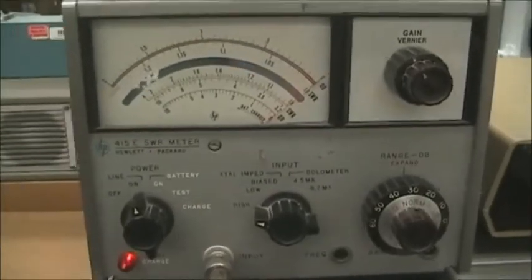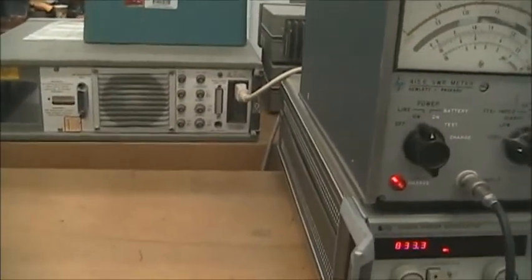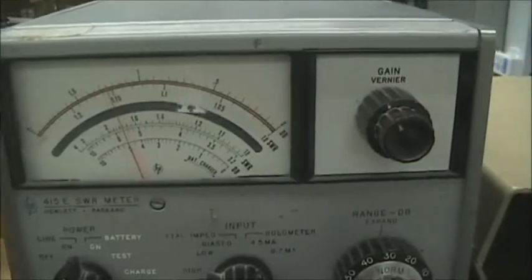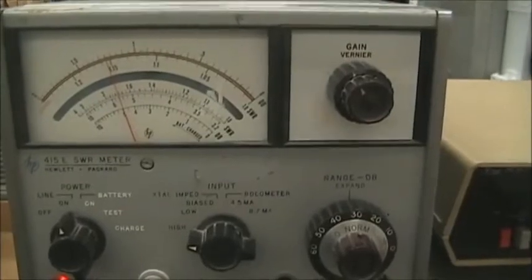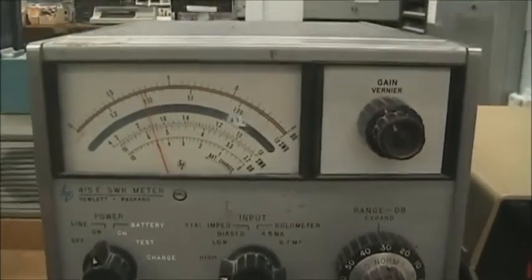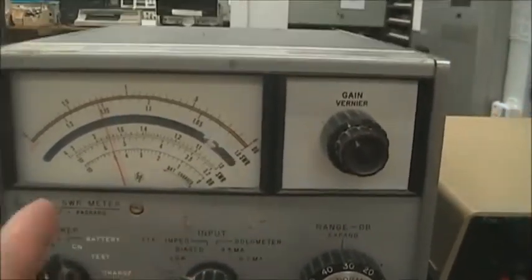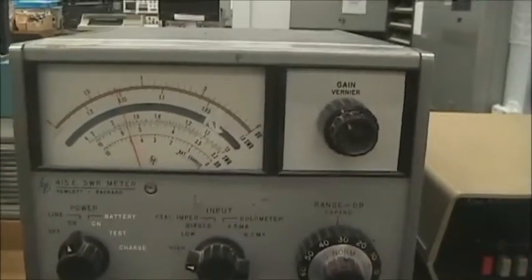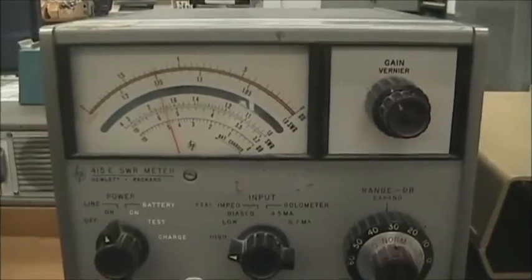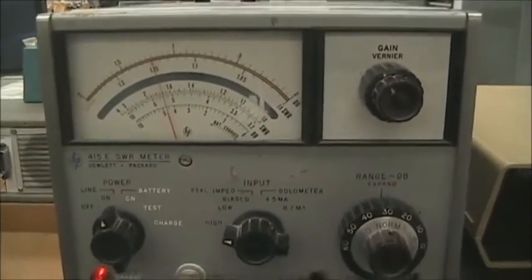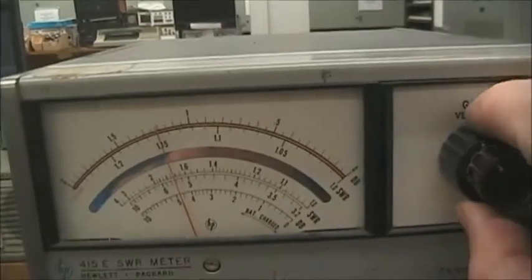So I've gone back to the peak, and now I'm going to insert the match or 50 ohm load on the system. Now what you'll see when I insert the 50 ohm is the signal dropped. And you say, well, it's a match, that's a better system. But remember, this meter is measuring reflections, and there's more of a reflection for a mismatch than there is for a match. In fact, if I move the carriage now, you'll see the needle is barely moving, right? So that means the system is very well matched, because the difference between the maximum and minimum is almost the same.